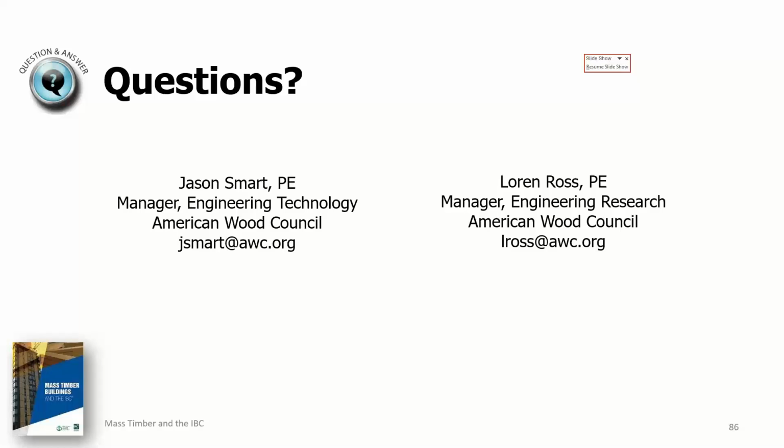But then it is, in a roundabout way, recognized in the NDS. Remember where I mentioned that you can have other approved materials like coatings or insulation, where a fire resistance contribution has been demonstrated. Again, that's going to require testing to demonstrate that. So that would fall under the other approved materials category in section 16.3 of the NDS. All right, great.